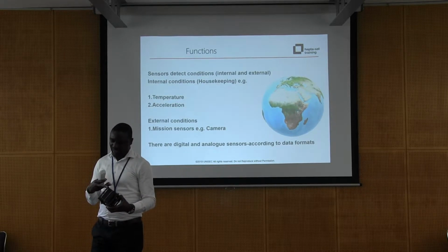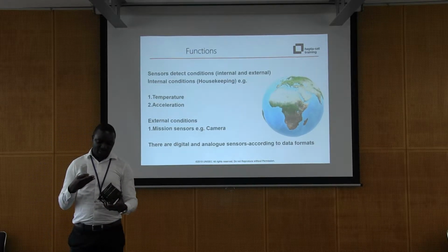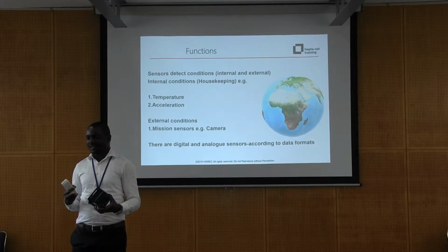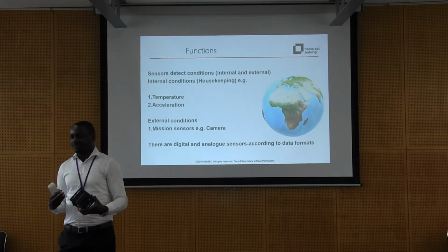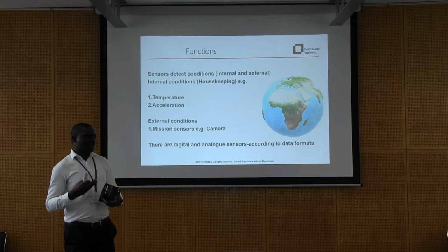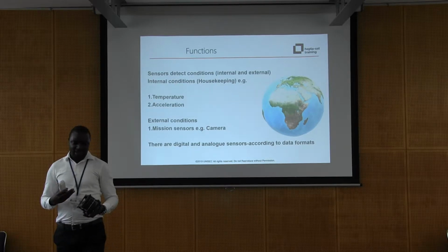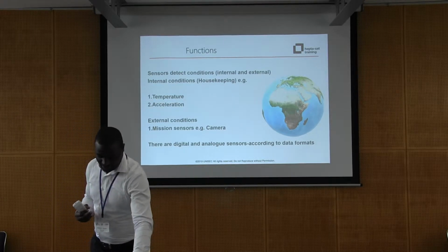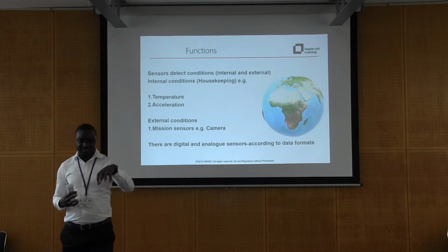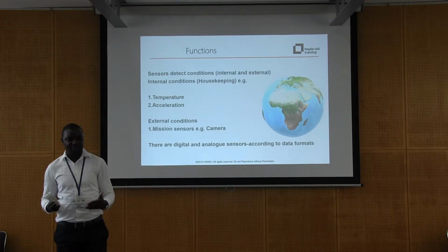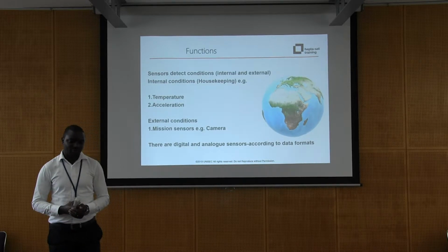Because as you imagine, you are loading it with different programs, and you want the satellite to do some functionalities. For you to know how the conditions are, sometimes you can overload your satellite with too many programs, and as a result, it will start heating up. So you need to detect the conditions within the satellite, and this is what we call housekeeping data. Within the satellite, it could be too hot to perform a mission. The battery could also be depleted, and it can no longer function or produce your mission data.